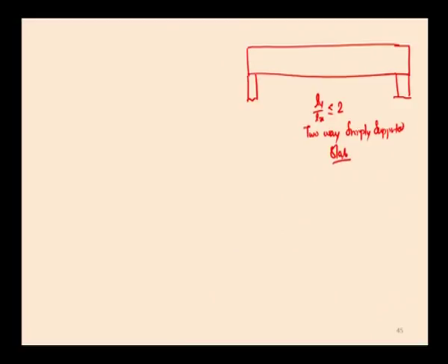In this case also, if it is a pure simply supported slab, if the wall is not going to be constructed over the slab, the main reinforcement has to be provided along both directions in the form of mesh. That is called the mesh form of reinforcement.